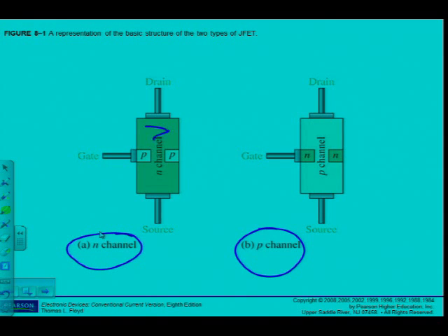The N-channel has got a large piece of N-type material with two small pieces of P-type materials implanted in it. It's got 3 terminals, drain and source, and the gate terminal are connected to both of those pieces of P-type material. It's just drawn this way for simplicity's sake. But it will become more clear when we're going to discuss the basic operation of this device.